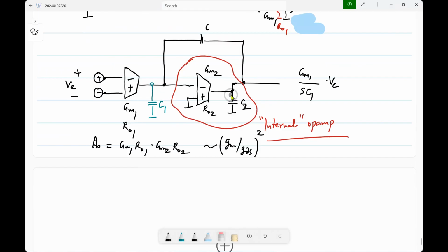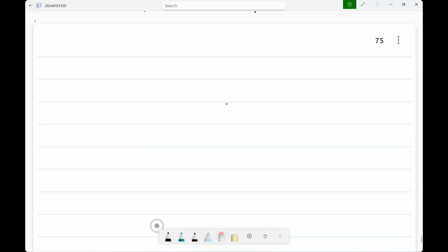Common drain or a source follower, right? But the source follower has very poor swing limit. Okay. So what is the best swing that you can get? Let's say you have transistor circuits and you have VDD and 0. What is the maximum swing that you can get?